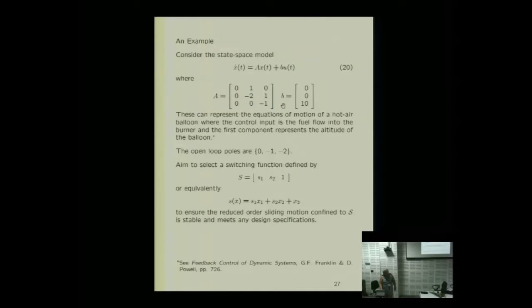Okay? So the model has the structure where the control signal acts directly on the third state, but there is no impact of the control signal directly on the first two states. The control signal only impacts the first two state components via the third state. We can see that such a system needs a controller. It's got a pole at the origin, so it's not desirable.